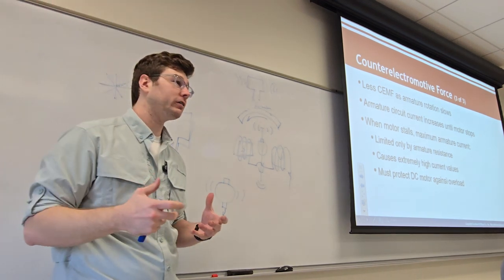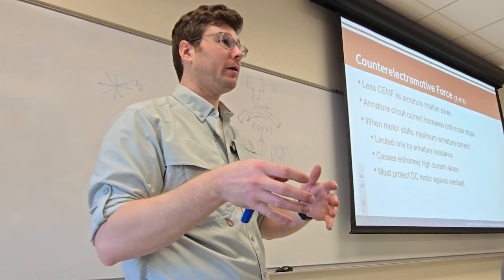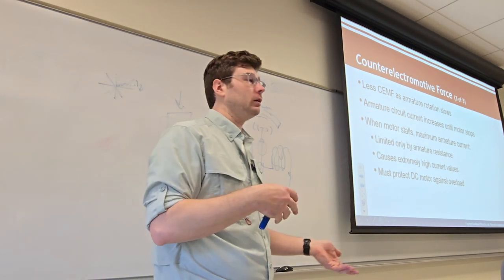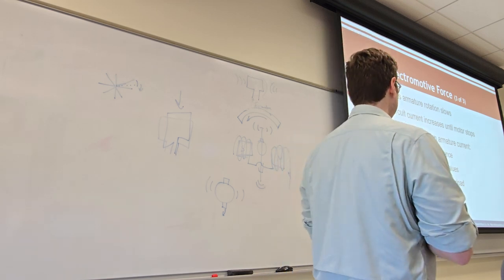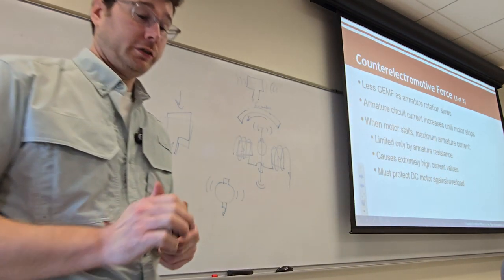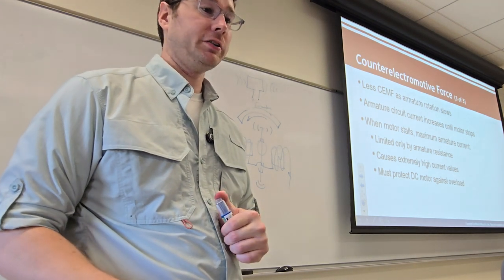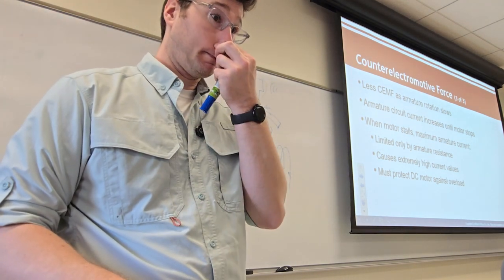So if we characterize that motor, we see some amount of voltage per some amount of RPM. We can get a really simple speed controller that way. We don't even have to have much instrumentation or sensors or anything. It's just the actual motor itself and a voltmeter, essentially.